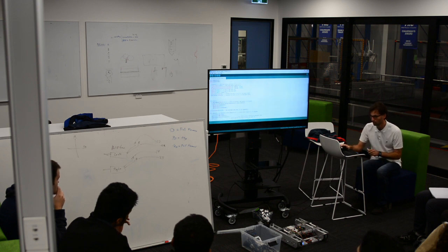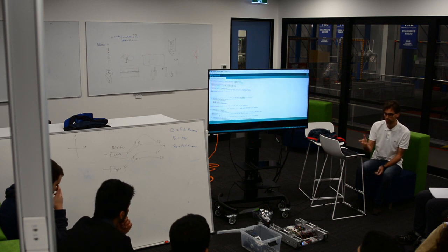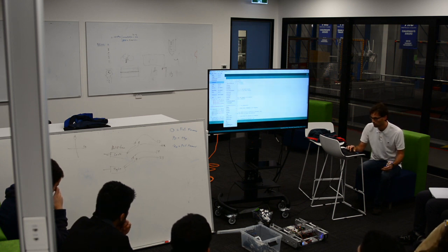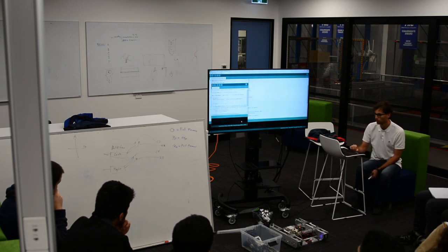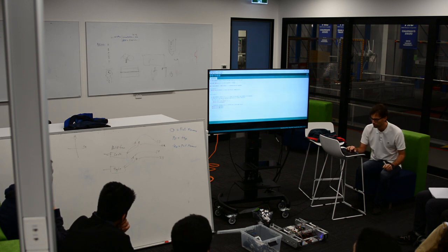Okay. All I want to do right now is check and see if we've got the motors running. And the way to check that, I've just used something called File. In Arduino, you always build from examples, right? So for every library that I've used, I go File, Examples. The first library we used was the Metro library, right? So I'd go down here to Metro, and I go SerialInterval. There's the code that I need. This is where I got all the code from. It tells me to include the Metro, set up the Metro, set up the serial, if serial Metro check. You just copy and paste this stuff. There's a couple little changes because there's some things that have expired, but anyway.